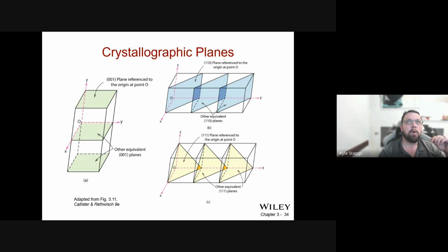That's because they are more like a 110 plane, because that is a safer way for the glass to fracture. Simple float plate glass fractures typically along 111 planes, leaving sharp triangular shards.